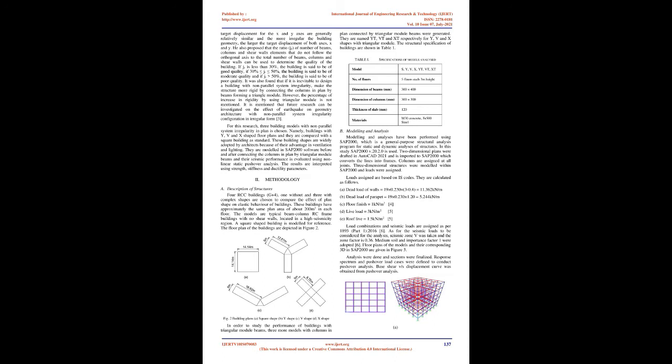When the earthquake struck, of the three blocks, Block C was more severely damaged than Blocks A and B because of the non-parallel irregular configuration in the two-way axes X and Y for Block C, compared to Blocks A and B, which is only on the X-axis. This made a significant contribution to the severe damage of Block C [2].